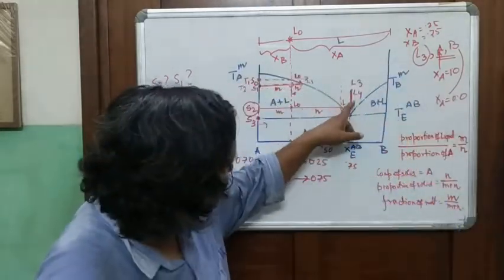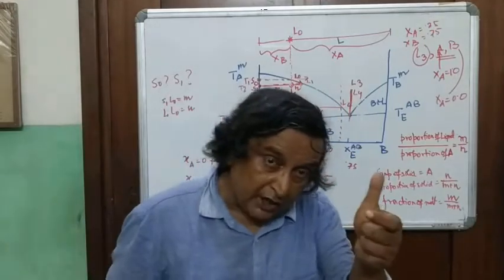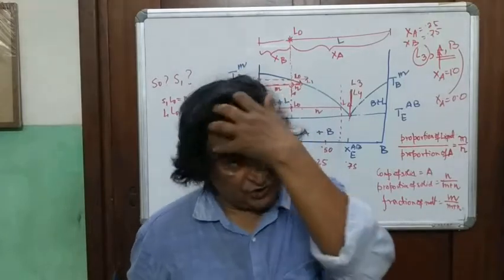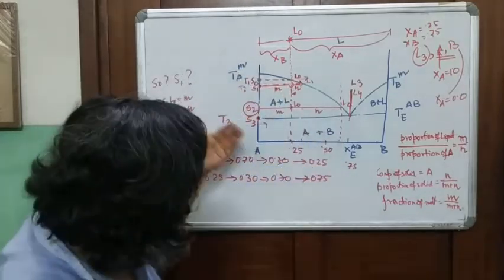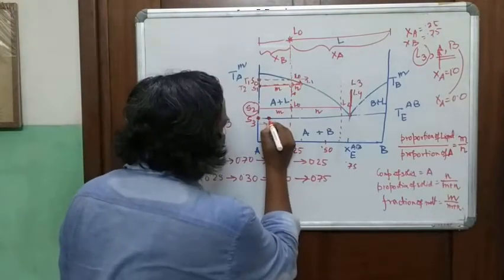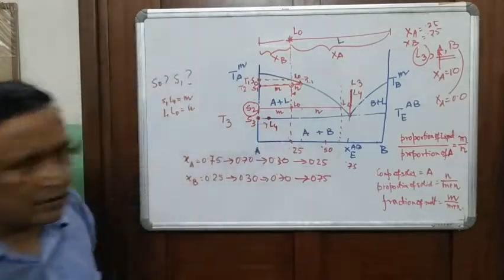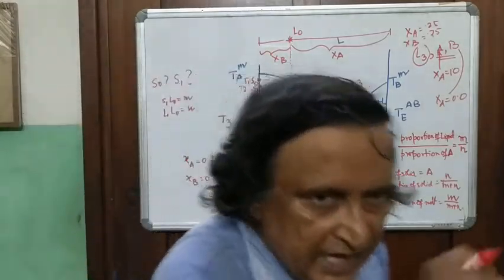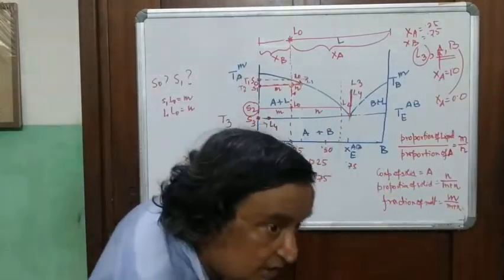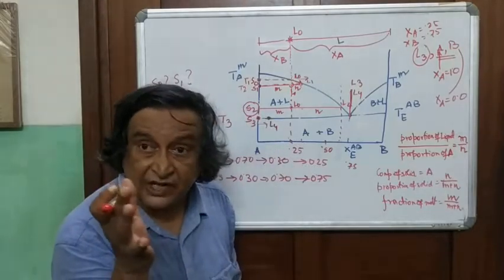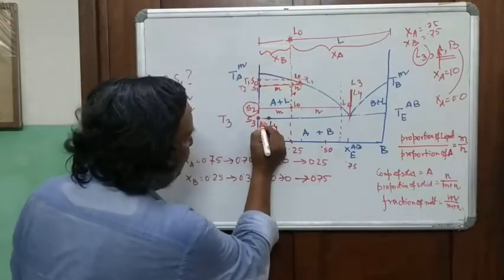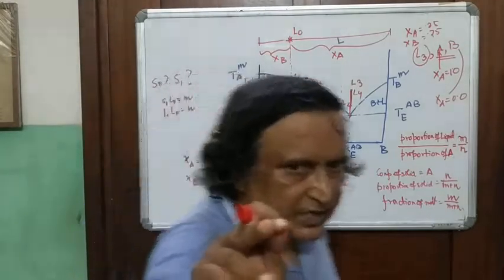When you move from L3 to L4, the proportion of the melt will change. The composition of the melt will not change. And the solid composition has to move inwards to L4. The solid composition has to move inwards along the eutectic temperature, because below this temperature melts no longer exist. So the solid composition has no way but to move along this eutectic temperature.